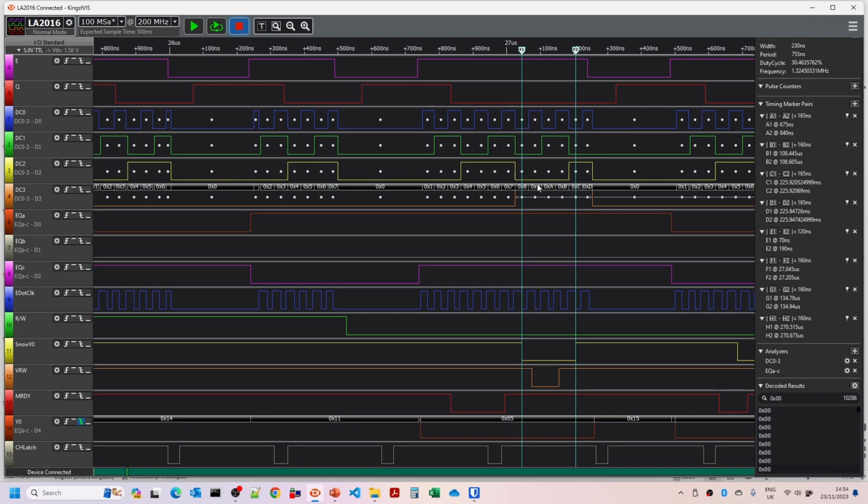Some of these things are slightly delayed, so although the clock cycle might get triggered earlier, by the time all the rest of the logic has triggered, it can be 20 nanoseconds, 30 nanoseconds afterwards. Remember, one of these clock cycles here is about 40 nanoseconds, and some of these gates have delays of 10, 15, 20 nanoseconds, so there is sometimes a little bit of a delay from when something's triggered.